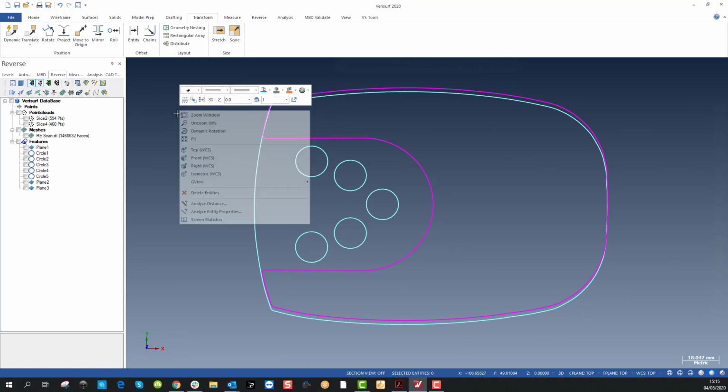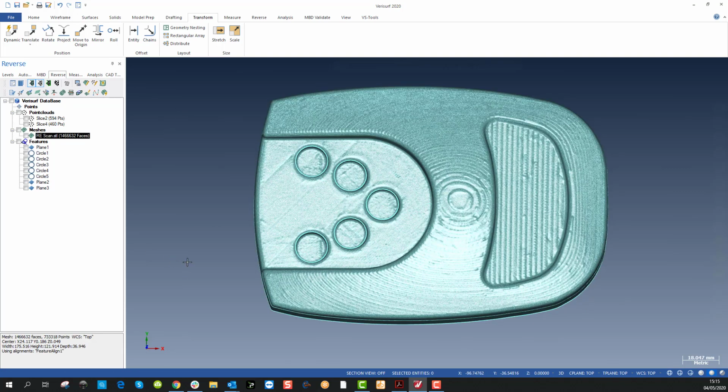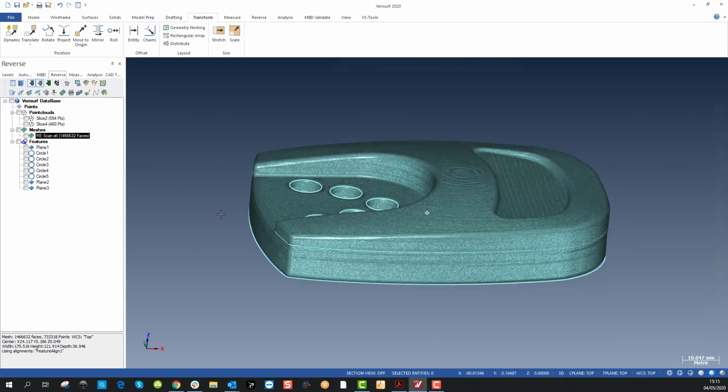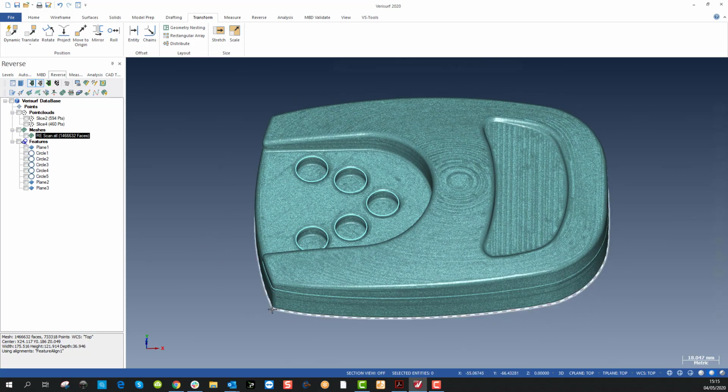So now we can click remove colors. We look at the mesh. There we go. So there's the slice directly on this plane, and there's the other slice directly on the bottom plane. Okay. So what else do we need? We can use this slice to drag and create a solid body. We have this slice that we need to just trim a bit to cut out the pocket here.